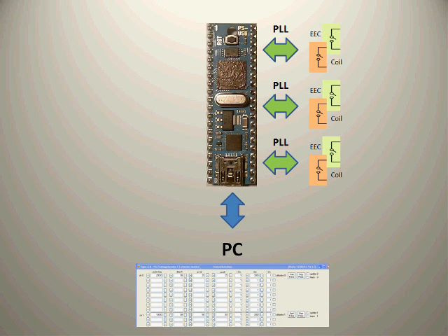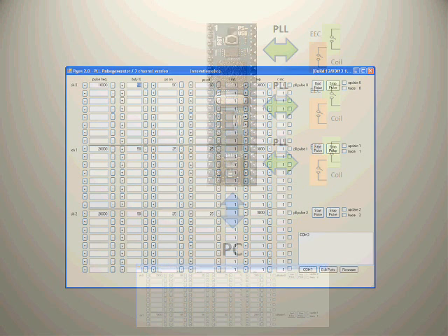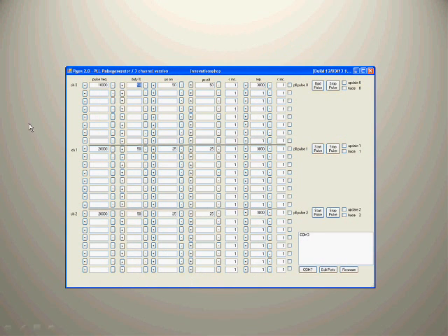For control of pulsing operation, parameter adjustment and parameter display, there is a Windows interface. Here in the Windows interface you can see the parameter input and display fields needed. Of course, frequency input, duty cycle input. You also have the choice to put in the parameters in microseconds on and microseconds off instead of frequency.